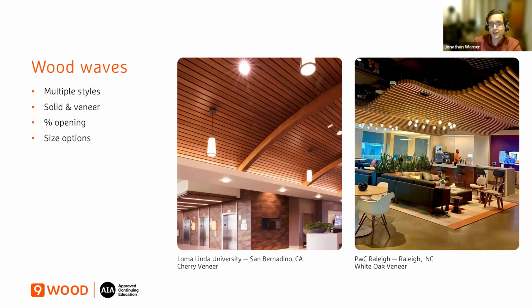And as I mentioned earlier, not just with solid wood, you can shape it as seen in the photos here, but you can actually get veneer members CNC'd to different profiles and shapes. There will be some cost impact to that, but if that's what you need to design, those options are available. Just find out early with the manufacturer if they have the capabilities of doing that and the budget impacts with a variety of different choices. And so lots of different things there.